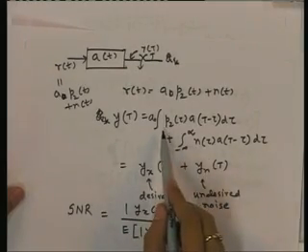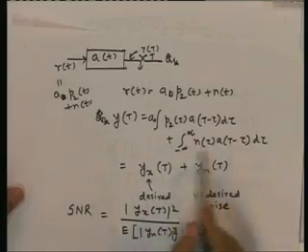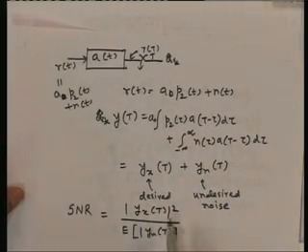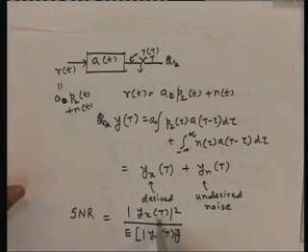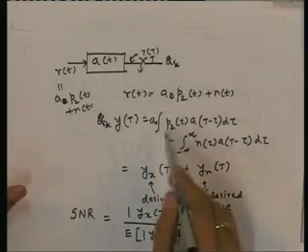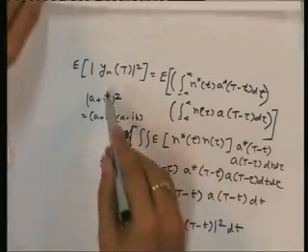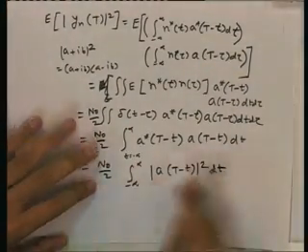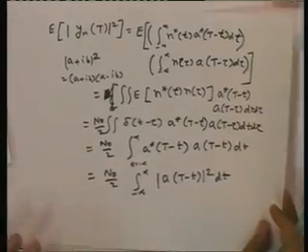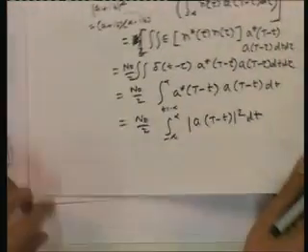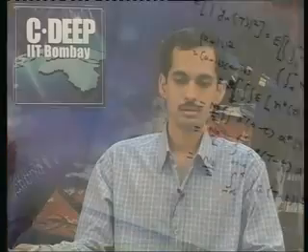So we want to maximize this scaling by this variance. So SNR is this: the energy of this signal part divided by the expected energy of the noise part. We want to maximize the energy of this by the expected energy of this. So, towards that we are now computing this denominator, the expectation of the noise part. So we will continue doing it. We have computed this, and then we will argue later that matched filter actually gives us this best SNR.